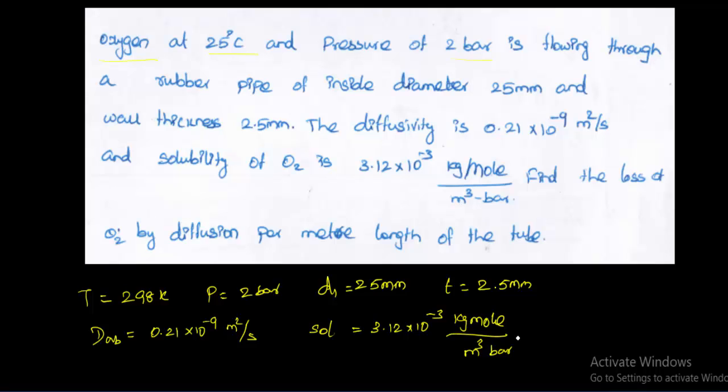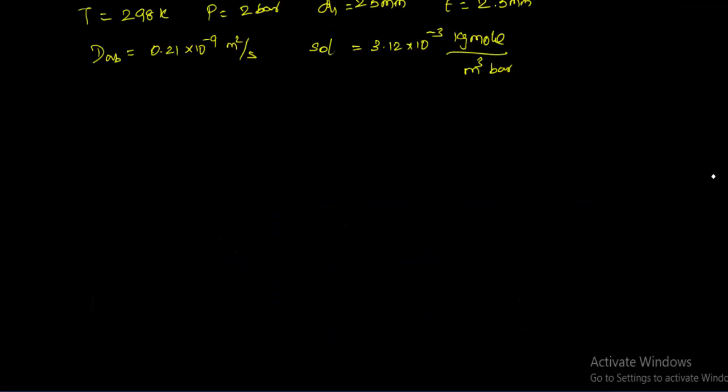Once you see a tube in the problem, you don't consider that it is an equimolar diffusion problem. You just consider a tube. In that tube itself, the diffusion happens to the atmosphere, so through the wall of the tube the diffusion happens. In this case you have to take the plane membrane problem only. First thing, once the solubility of the component is given, you have to find the molar concentration.